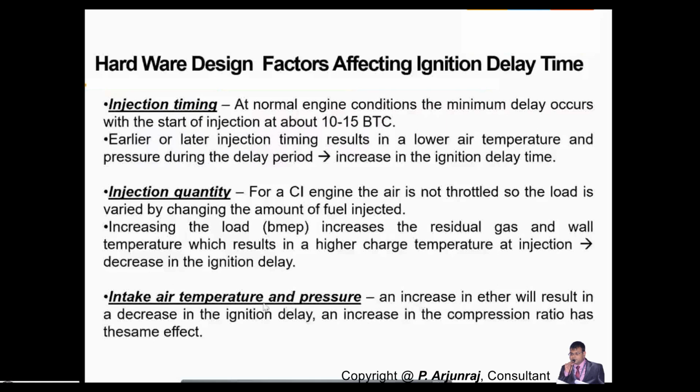When you use EGR, the exhaust gas gets mixed with the air. That will increase the temperature of the incoming air itself. When you increase the incoming air temperature, your ignition delay is going to be lesser.